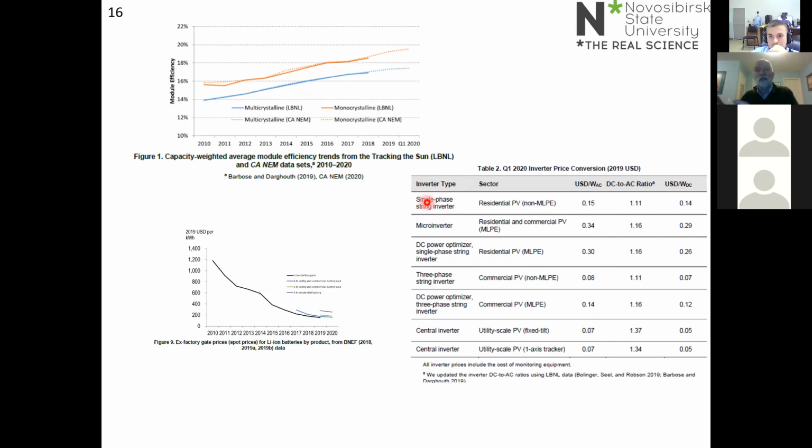With a wind turbine, you don't have much choice. You know, each wind turbine has a generator in the nacelle at the top of the tower. So you're more or less forced to do all your power electronics, or your conversion into good quality alternating current power, at each wind turbine. But with a PV system, you have a lot of choice.